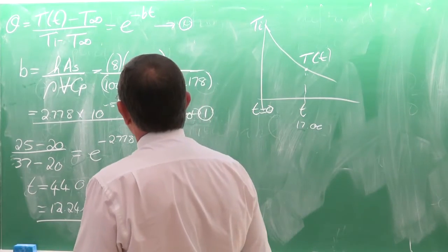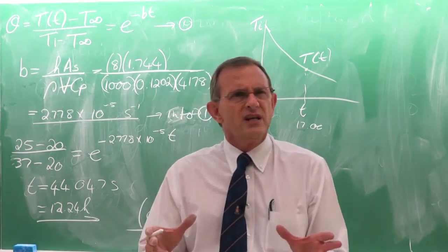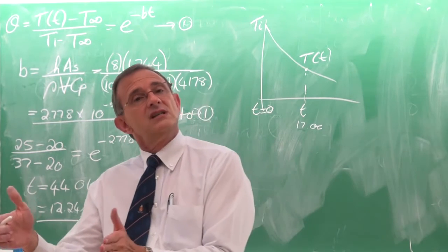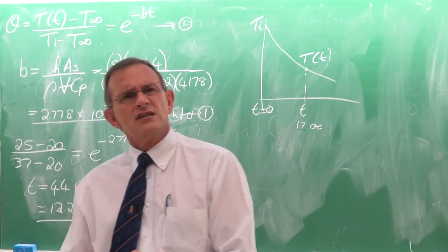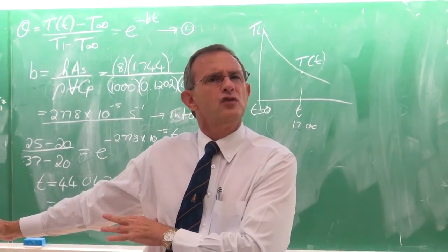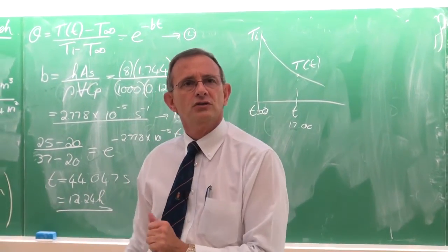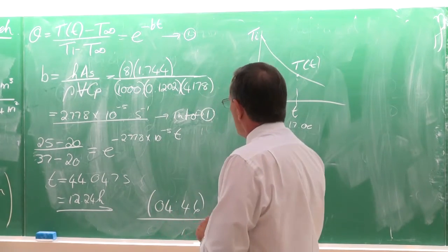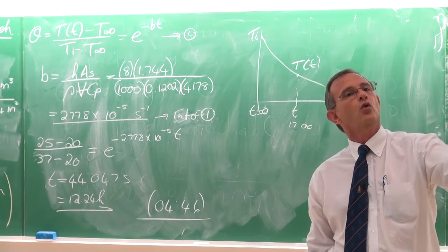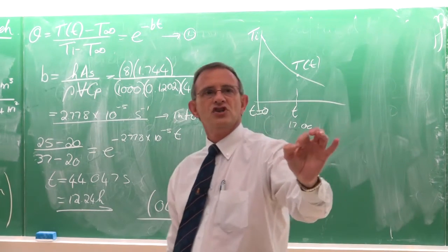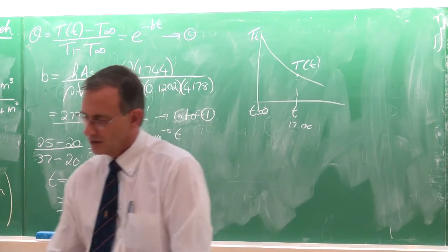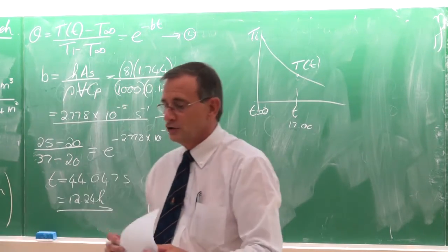So in this case, with the Biot number 0.89, what does it mean? It means that the resistance inside the body is approximately the same as that of convection. So as an engineer, I should be careful. But it's a first order of magnitude calculation. Most probably, and we will see later on, it will not be out by a factor of 10 or 100. In many cases you just want a first order calculation, and then this can help. Right, now let's do it the right way.